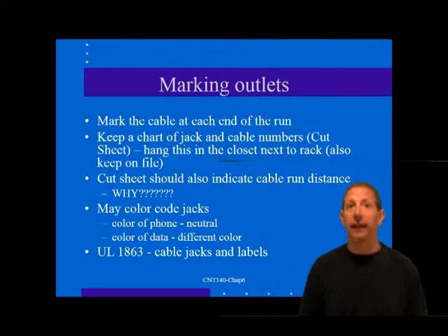for their modular inserts. In theory, the color markings allow one to easily differentiate between, say, voice and data jacks. However, there are really no universal standards for these colors. What may seem to be a logical color choice to you could be the opposite of what someone else might choose. You might simply want to leave all the jacks in the same neutral color as the faceplate and differentiate the jack's functions with the plate markings. Alternatively, you may choose to leave the telephone connector neutral and use a different color for the LAN jack.